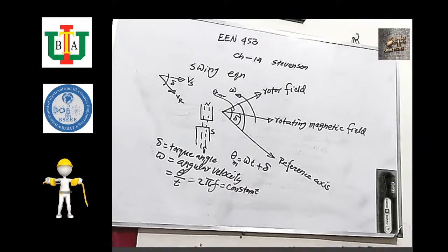The power system controller does the job. It may be a PID, proportional integral derivative controller, PI controller, adaptive controller, self-tuning controller, model reference adaptive controller, or neuro-fuzzy controller. Many types of controllers have been established by researchers, and their job is to bring the machine back to synchronism after suffering a disturbance.